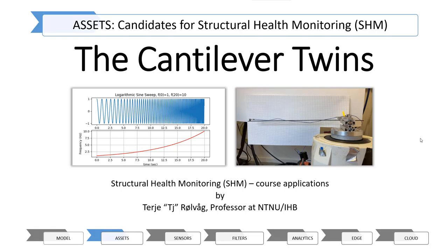Good morning everyone, I'm TJ and today I'm going to demonstrate structural dynamics in a cantilever beam. This is an application I'm using in my latest course called Digital Twin Technologies for Condition and Structural Health Monitoring. I'm using a shaker and a sine sweep function to visualize the lowest three eigenmodes of this cantilever beam. And I'm using a high-speed camera to record the mode shapes during excitations.